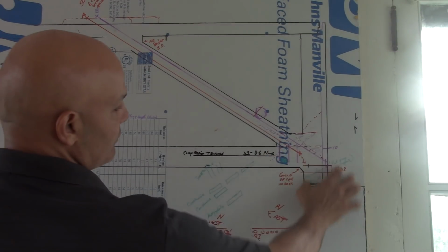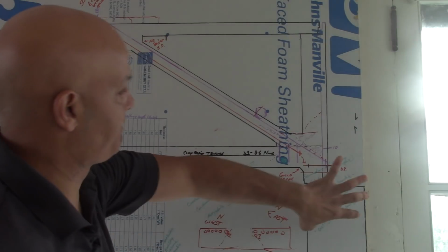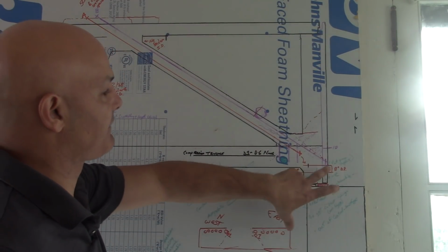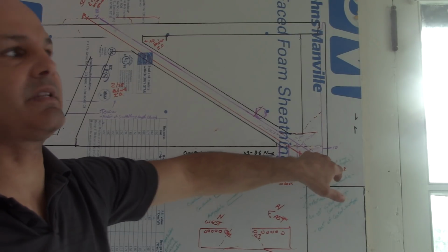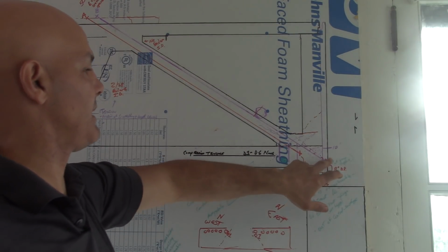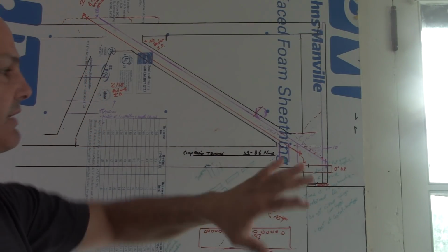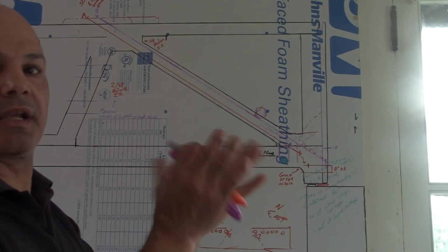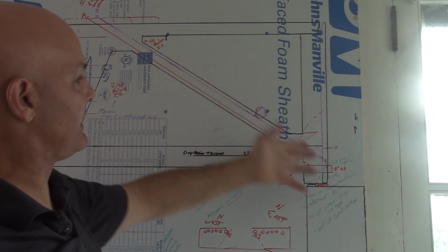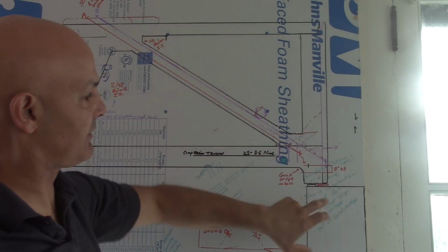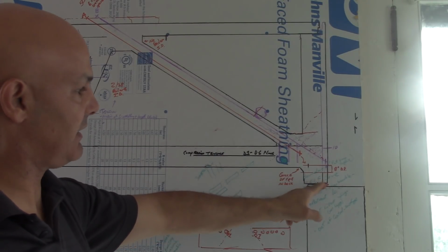So this broke free, it dropped down whatever amount of inches. They then attempted to put this back, they claimed that the forces were put back on, 280 kips or something like that, 256 kips, 288 kips, whatever it might be. But all those cracks, they just don't go back together. This is not opening a book and closing a book. There's concrete there. It doesn't just blend back in. And we still have it 4 inches down. This doesn't have the ability to jack up the end a few inches.